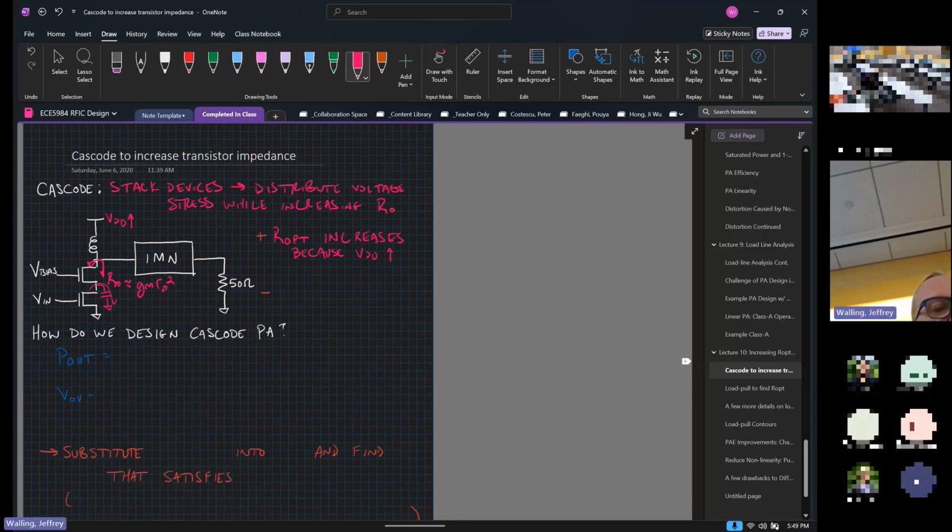Okay, is there anything negative other than the things we've already kind of talked about or touched on? The swing gets a little bit worse. If you increase the VDD, is it really fair to say this gets worse? Like, if you're saying you increase the VDD, but yeah. Well, this is a very specific element of the swing that gets worse. What happens is I now have two devices that I need to keep saturated if I'm trying to keep these both operating as current sources. And so the knee voltage of this whole thing increases by quite a bit.